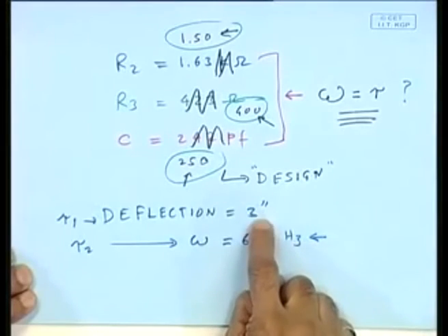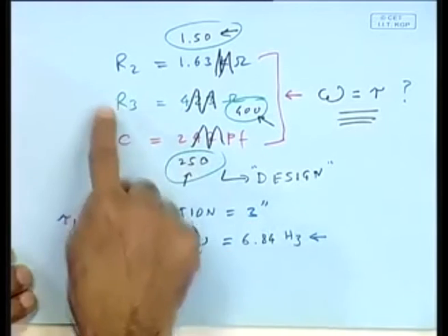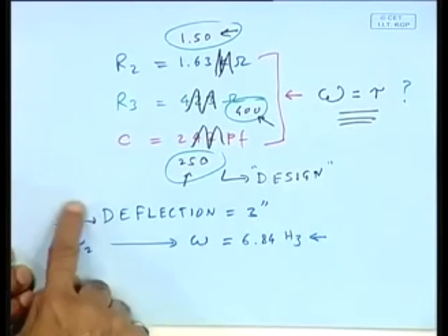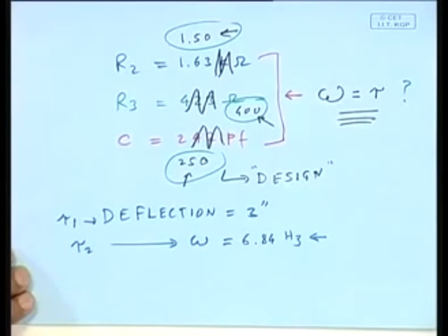You can find out, by putting certain values for R2, R3 and RC, what value of performance you're going to get. You can derive that using SPICE. You can do the same thing for this one also. It's not very difficult to do that. So I'm able to simulate that. I'm also going to be able to simulate noise by using a little Monte Carlo. I can simulate that noise.